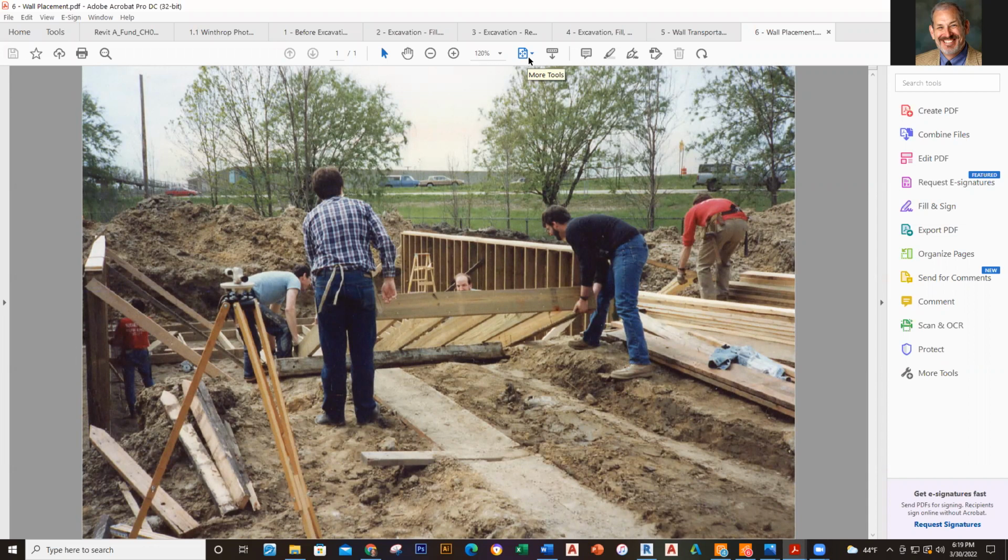Another thing about stainless steel is if you've never hammered in a stainless steel nail, what will happen is they are much more likely to bend because they're not hardened the way other nails are. So that's part of what you deal with there. So anyway, we used stainless steel nails to attach all these. That's a pricey endeavor, but overall it's a very cost-effective way of doing things.